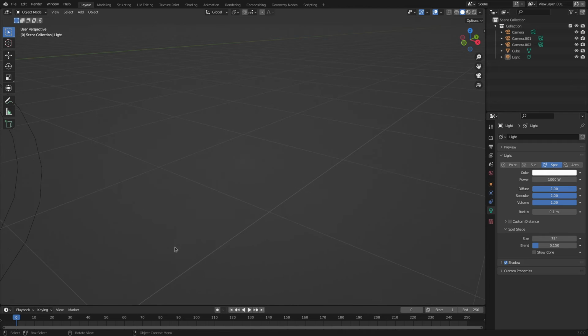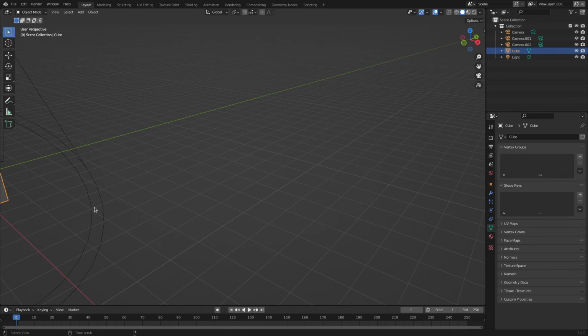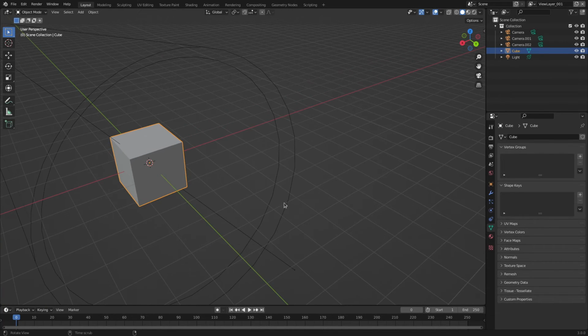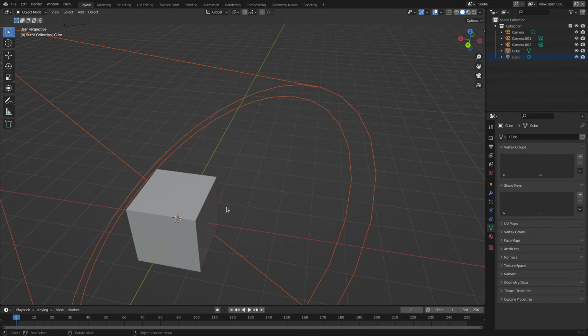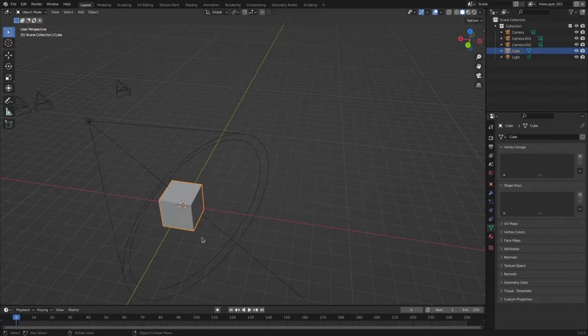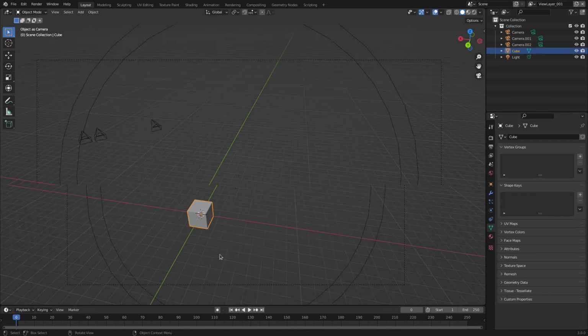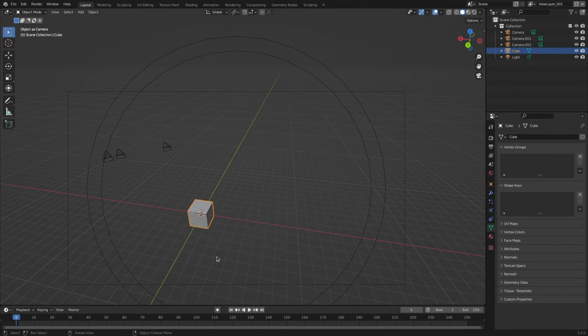So if we select that guy and look at the scene from there, and I want to call the camera to where I am, remember this is pretty simple to remember, it's Control-Alt-0. And now the camera is where I'm at. Only,